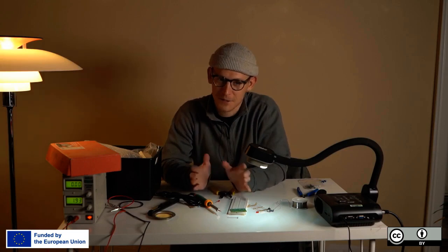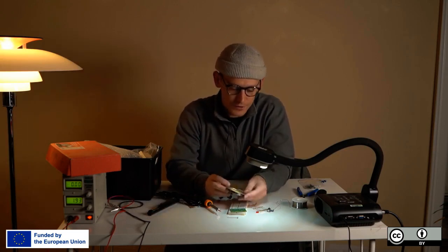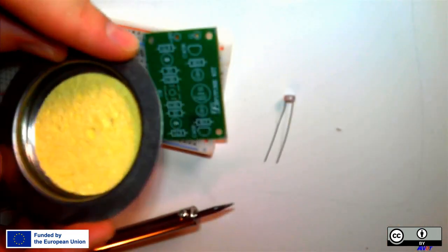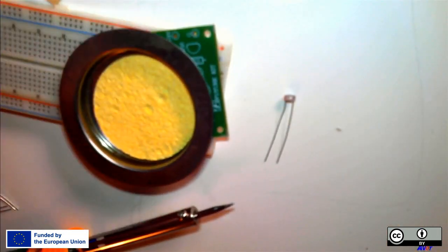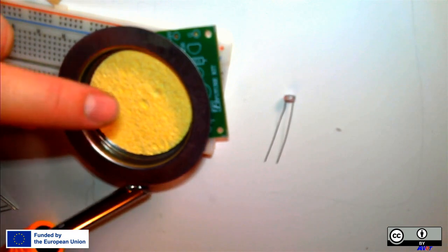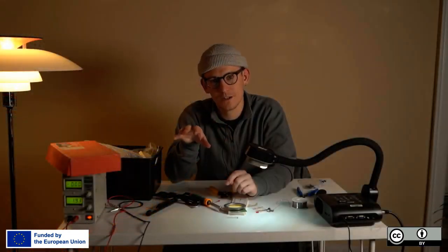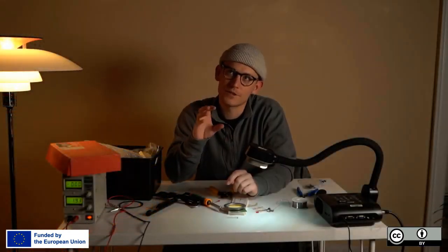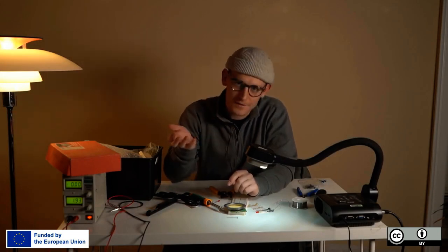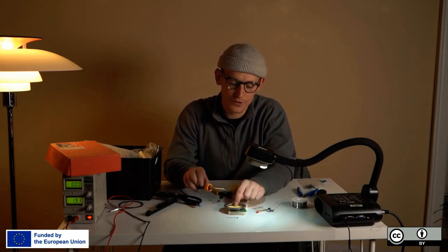Also just simple sponges like these. Add water to them and use them to remove the extra soldering tin from your soldering iron as you're soldering. As we continuously heat soldering tin, we will have a reduction in the flux that is in the soldering tin. So you can say the soldering tin kind of goes bad after some time when it's been on your soldering iron for a while. That's why we will circulate it using these to remove them slowly, and then just keep using fresh tin.